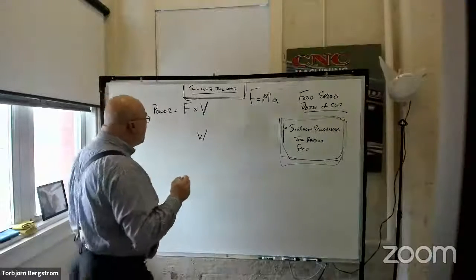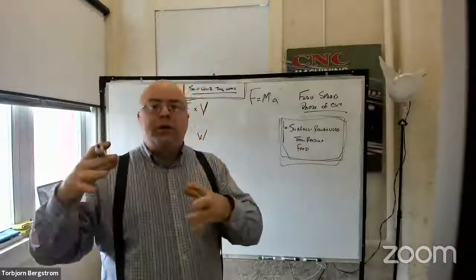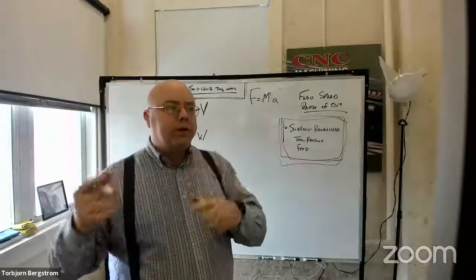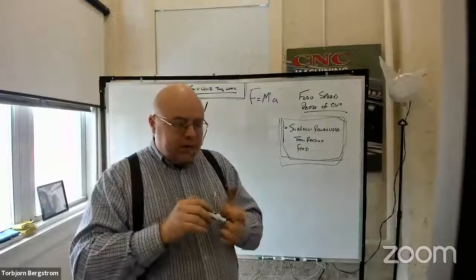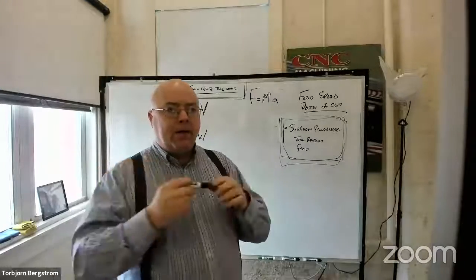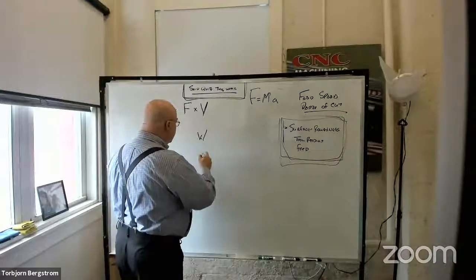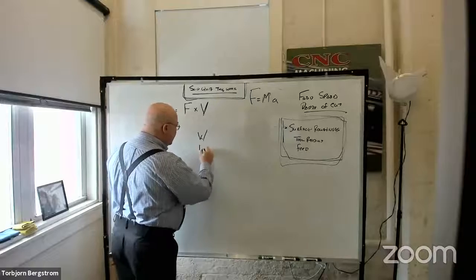There's a material property, and it's not just the hardness, although the hardness probably correlates with this property, but we call it the specific energy for cutting, or specific power for cutting if we're calculating power. And so we'll call that KP.